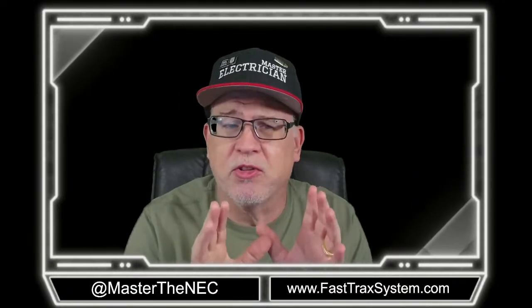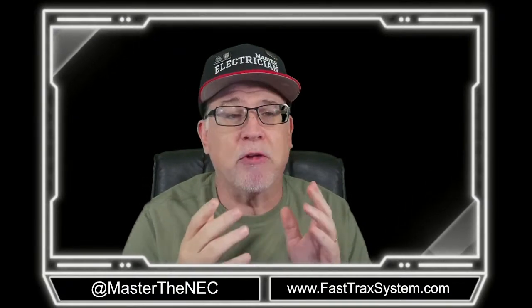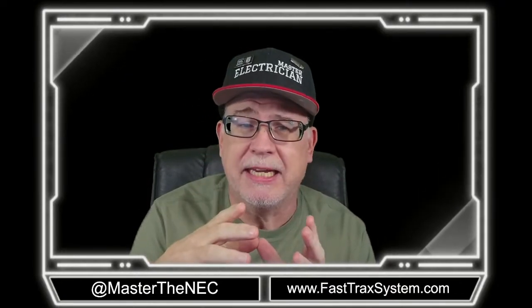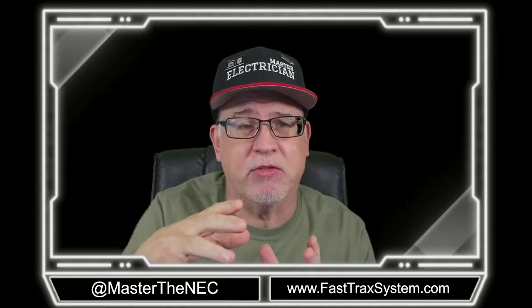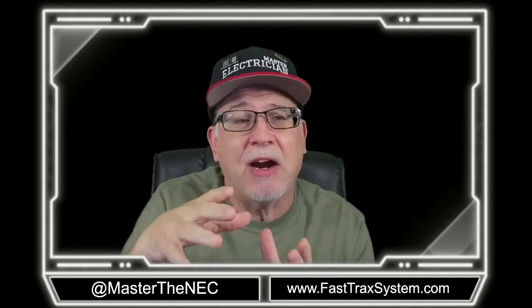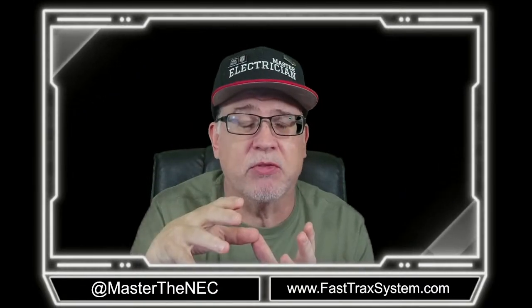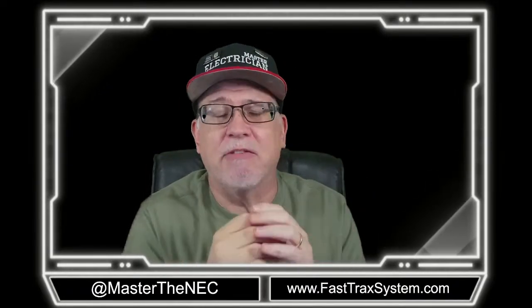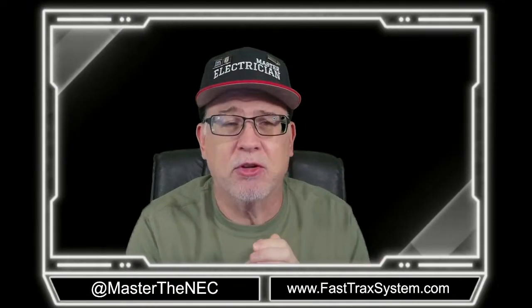Then there's also part 2, and in part 2, we focused on sizing the grounded conductor to the service, and we focused on a single raceway and how you might size the grounded conductor in a single raceway, and we included things like wireways into that, and so you could have multiple sets all in a single raceway, and you would have a single grounded conductor and how you would size that, remembering that that grounded conductor also is providing fault current back to the source.